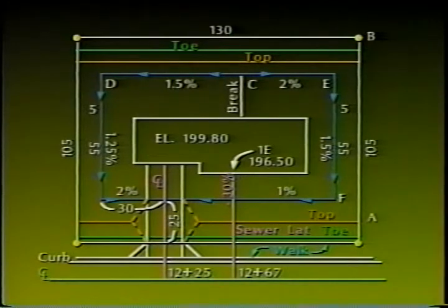From the site plan, the distance from the top of slope to the property line is 20 feet, so the dimension from the property line to the toe is 20 minus 2 times the change in elevation between the top and the toe. As you can see, a lot of time and effort can be saved by proper planning and organization.